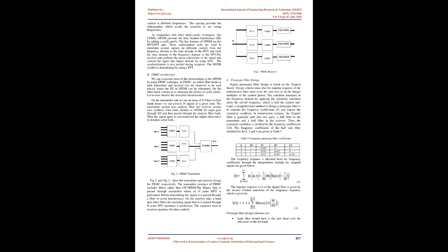Once the symbol has been allocated to each of the subcarriers, they are phase mapped in accordance with the modulating technique. Different modulation schemes can be adopted based on channel condition, data rate, robustness, throughput, and channel bandwidth, i.e., QPSK, QAM. Modulation to OFDM sub-channels can be made adaptive after getting information and estimation of the channel at the transmitter.